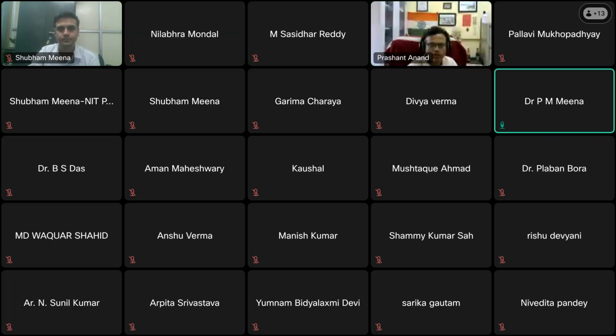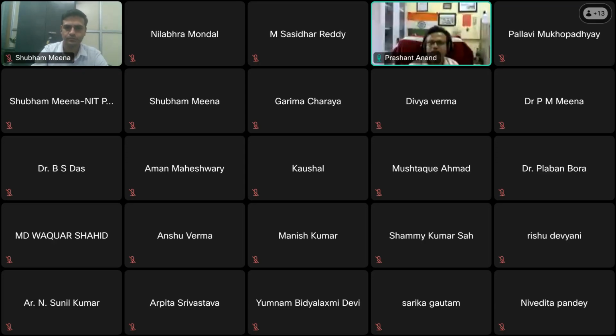Even though the surfaces are shiny and look reflective, the way it is designed, the color is selected to absorb. There are two kinds of technologies. When I was working on the IIT Jodhpur project, there were two technologies: solar photovoltaic and solar thermal. You may be confused between them. In solar thermal, there is a reflector and a concentrator, and the concentrator tube has some kind of liquid. The reflector reflects solar radiation towards the concentrator, so in that case a lot of reflection is happening. But in the case of conventional PV, the purpose is to absorb energy.